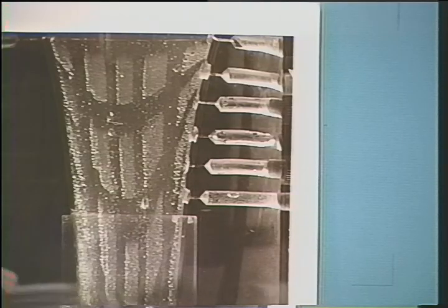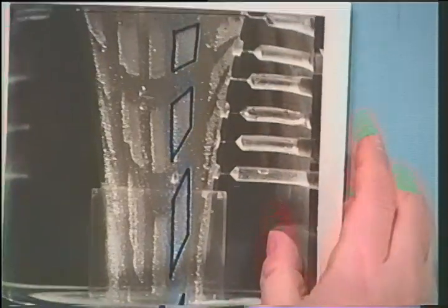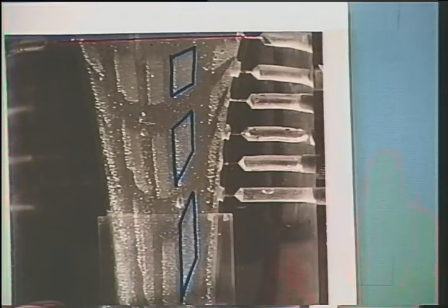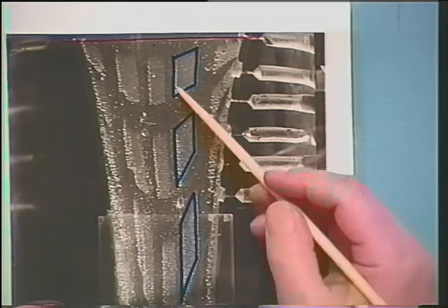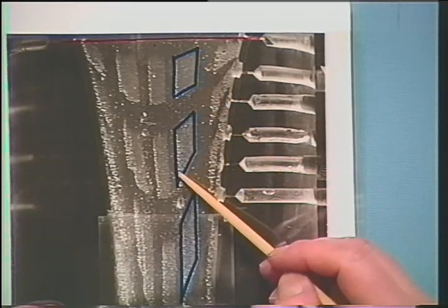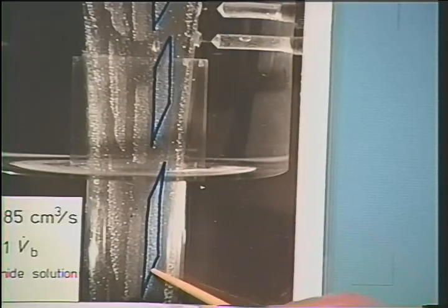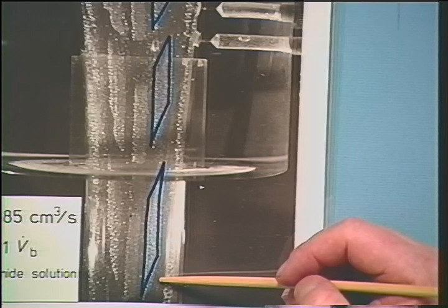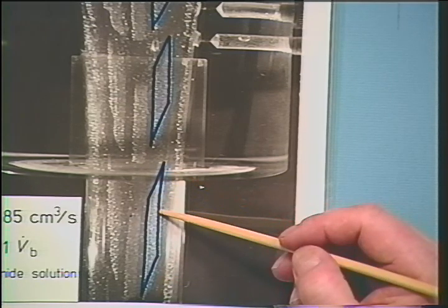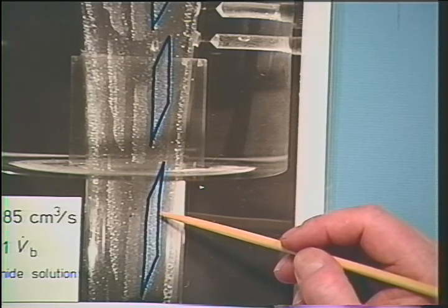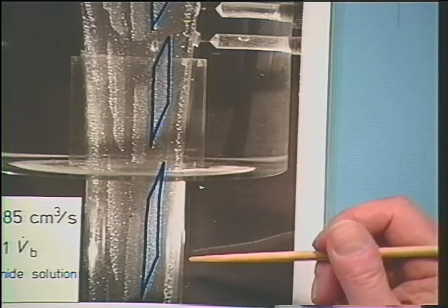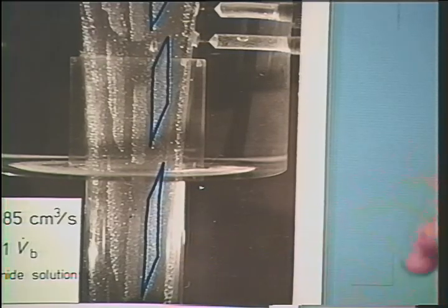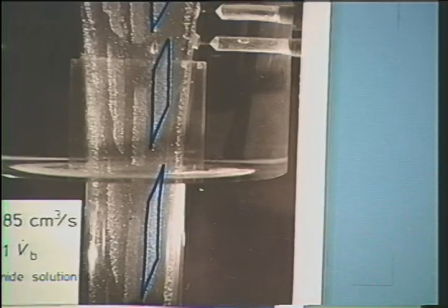And the residence time of those bubbles is changing in time. Let me draw some frame around those. This is the set of bubbles which just has been released. This is at a later time, an even later time, and even later time. You can see that the burst of bubbles is elongated because it's a flow which has acceleration in there. And the angle is changing because we are shearing. There's a shearing deformation of this material. Now the question is, how can we describe the strain tensor in that type of flow using the same framework which we used before?